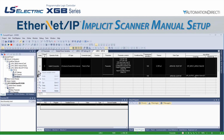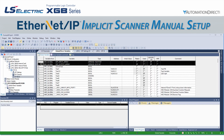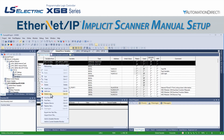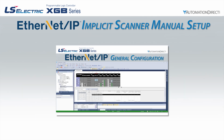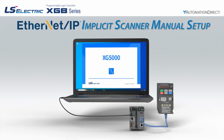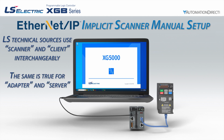I have removed our original message, GS20 adapter, and input and output variable arrays from the project to allow us to start from scratch. To set up the PLC as an implicit scanner, we first must configure the EIPT module and the peer-to-peer connection. These are both covered in a separate video. It is important to note that the LS software and documentation may refer to the scanner as a client and the adapter as a server.